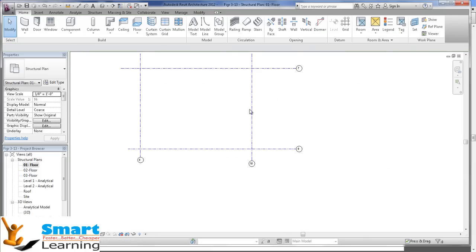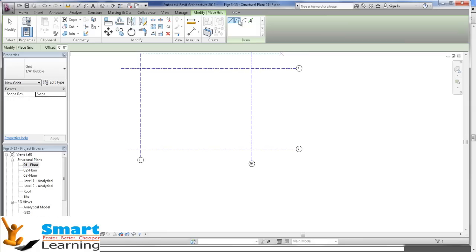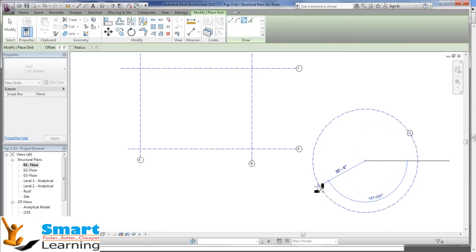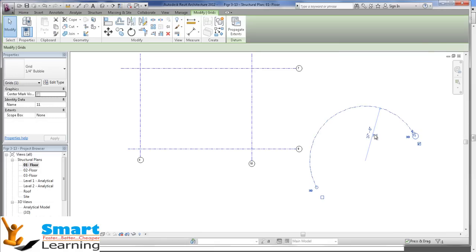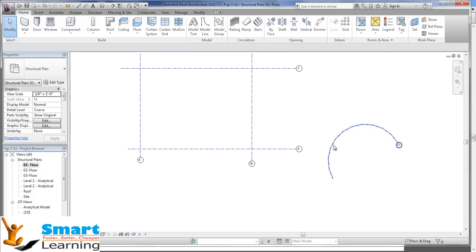Now we'll look at the grid with the other formats, which are center or start or end. If you go to the center and you go for the grids, then you can have the radial grids in the requisite directions, and here you can set your radius, and when you click it here, you will be able to assign the required properties with respect to a center.